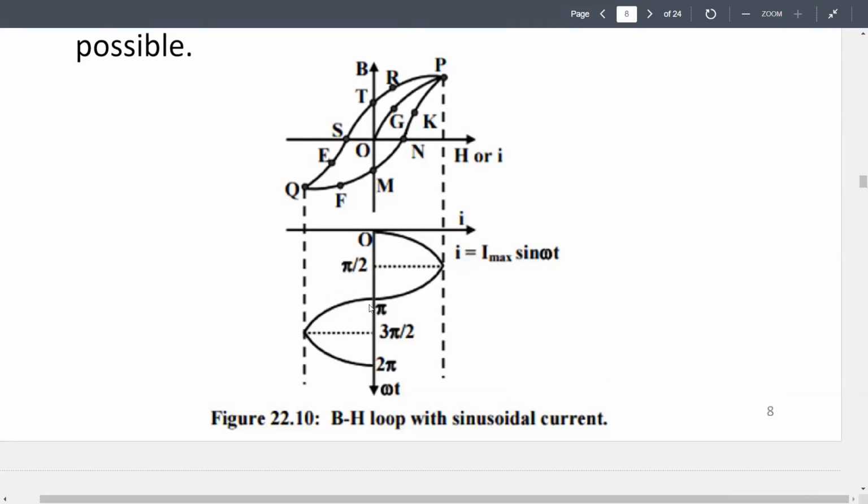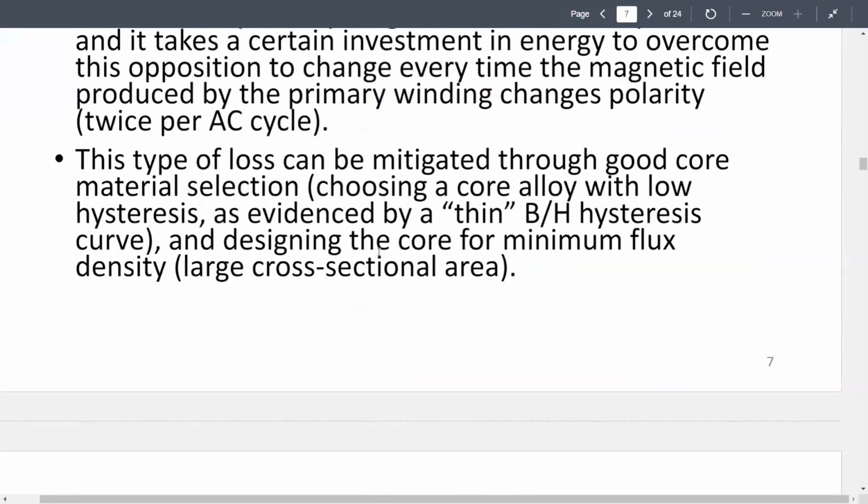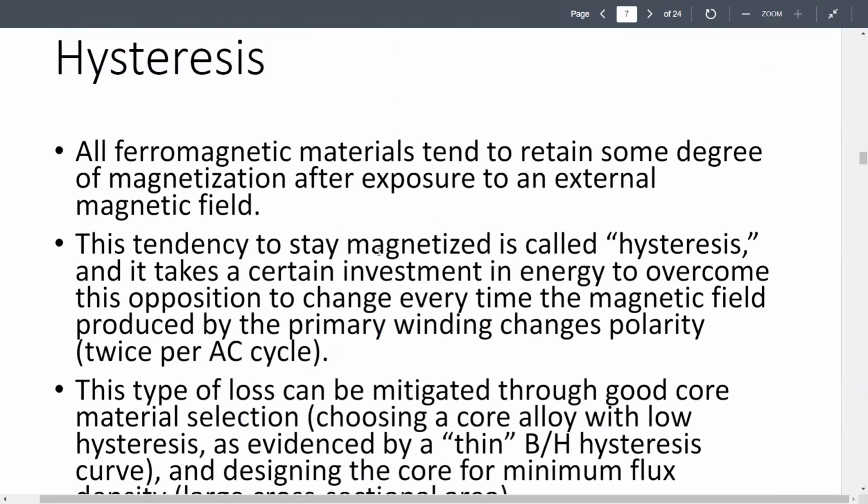But after some time, when it reaches zero, it's supposed to be demagnetized too. It's supposed to act like iron, not a magnet, but it doesn't. That is the problem. If the residual magnetism is too much for that type of material, then it's not good for transformers.